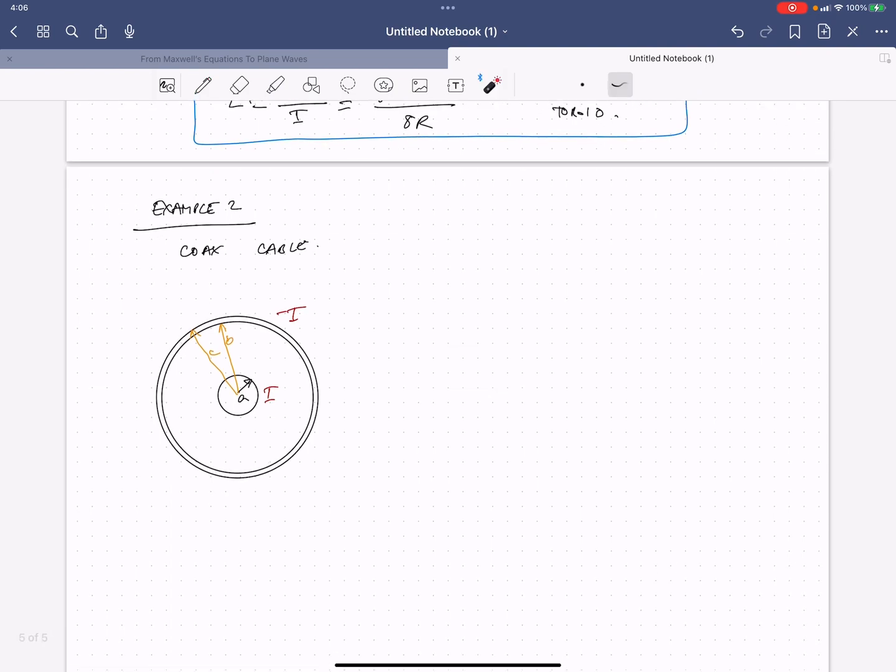So again, you'd have to have a bunch of different sections. And we'll see that the flux linkage will only be complete. So we have this section, we have this section. We saw this when we did the magnetic field calculations. And then the third one is the shell section, and in a perfect coax cable there's no magnetic field outside, so there's really three sections, and we'll see that the flux linkage will only be complete in one section and will be incomplete in the others.